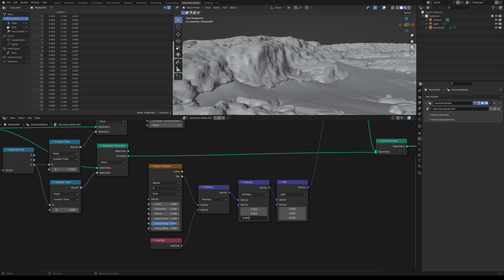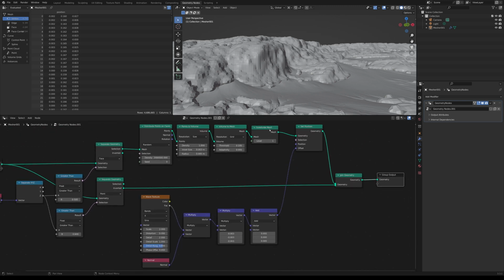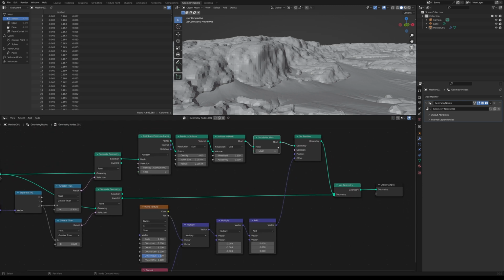And you can see how now it's shifting this and kind of doing a push in based on the strength of this texture and kind of what this texture is doing. So we'll probably have to play around with this bit just to see good values that give us a lot of detail. And I might have to also increase my subdivision of my mesh here so we have more geometry on the faces to add detail to.